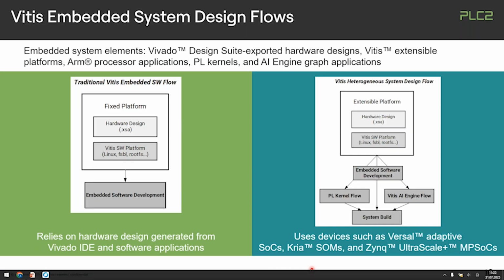And one of the most prominent stepping stones there is that you start off with a hardware design that cannot by nature know what will be asked of it until later, because you have not defined the AI engine, vector processor programs and everything like that. You have not defined the CPU requests onto the hardware. So what the heterogeneous design flow offers in this case is you can create a very traditional hardware design in Vivado, but you will not completely define it, in the sense that some things get attached to it later only.